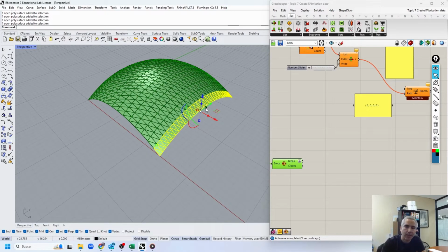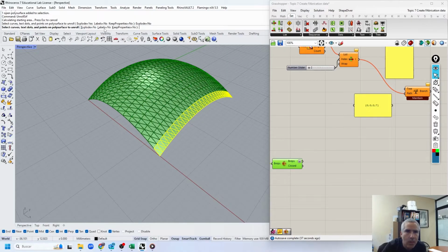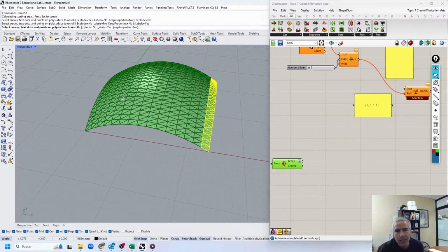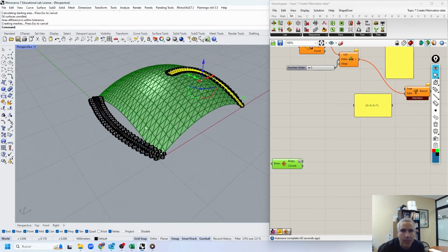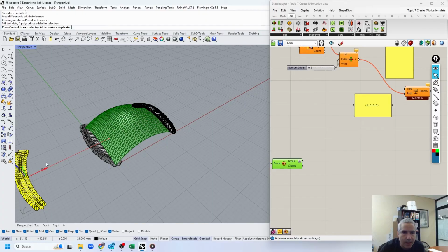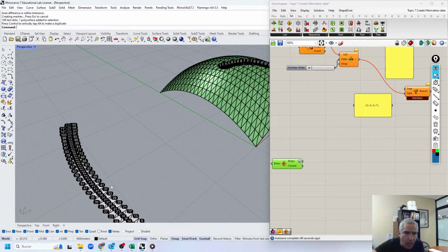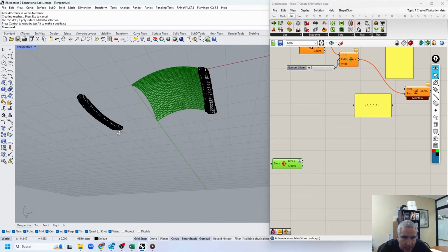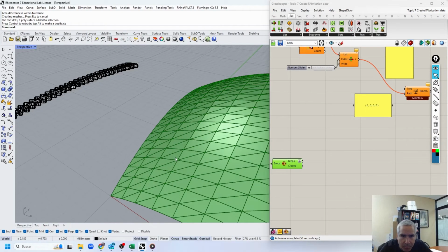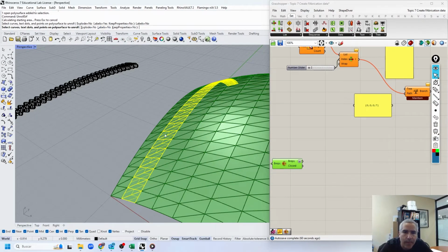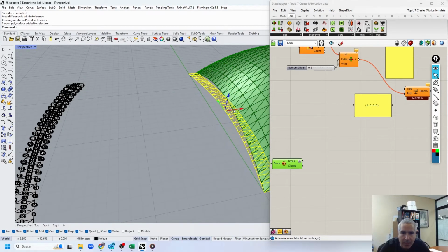And I don't know if you know Rhino, but Rhino has a very powerful command called unroll surface right there. With unroll surface you can do explode no, labels yes. If you do an unroll with Rhino, it takes a poly surface, unrolls it, and develops it into a flat configuration on the C-plane so that it's a flat panel. I'm going to do that without the labels. And as you can see, that's a flat panel.